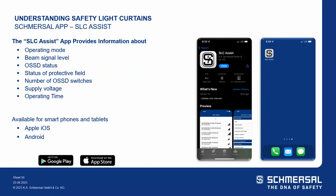We talked about Bluetooth. The Bluetooth is integrated into the 440 series of light curtains and grids, as well as the 440 COM series of light curtains and light grids. So it's the SLC Assist App that will give you information about the operating modes, the beam signal strength, your status of your OSSD safety outputs, the status of the protective field, the number of OSSD switches and the cycle counts, the number of times those outputs have been switched on and off, your supply voltage information, operating time.